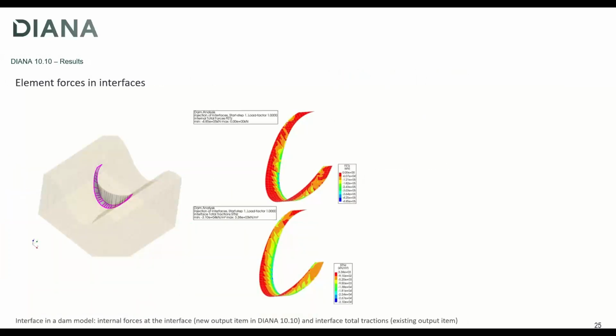It is a new result item, element forces in the interface. In the past, we had element forces in the interface, but that was available only in the global direction. But for certain applications, like the interface forces between the dam and the foundation, it is particularly useful to get the element forces in the local direction.